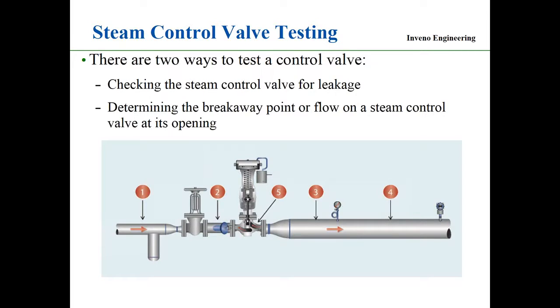Because I'm starting to set up a PID loop. And the PID loop assumes 4.0 milliamp is 0, no flow, and 4.4 milliamp, there is flow. If I have a dead band down here on the PID loop, the valve doesn't start to pass steam until 5 or 4.8 milliamps. It does start to cause some issues with the PID loop, setting it up and tuning it.